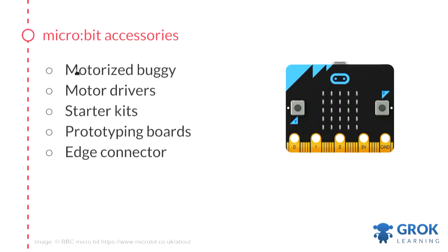And now an ecosystem is popping up, just like Arduino, which is wonderful. A company called Kitronic in the UK is doing things like motorized buggies, motors, lights, NeoPixels, the whole works. And it's easy just to connect the pins. One thing that's worth mentioning, and the reason I put another picture up here, is that these pins are a little bit annoying other than the alligator clip ones. So a must-have accessory is the edge connector, and it's basically a little slot that it goes in and exposes all these pins on a breadboard compatible board.